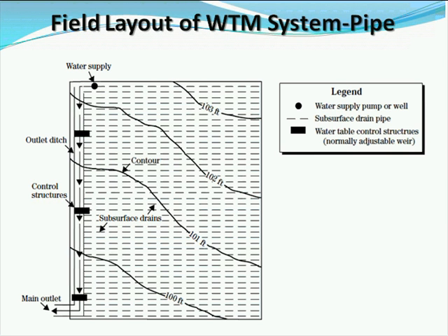You can see that you have them periodically, and so this would be the difference in this and what Ruth was showing, which would be, rather than the pipe drains emptying into a larger diameter pipe and conveyed down the slope with periodic water control structures along that main, with this, we've got the individual pipes dropping the water off into an outlet ditch,